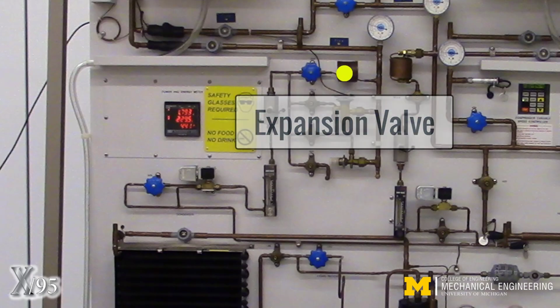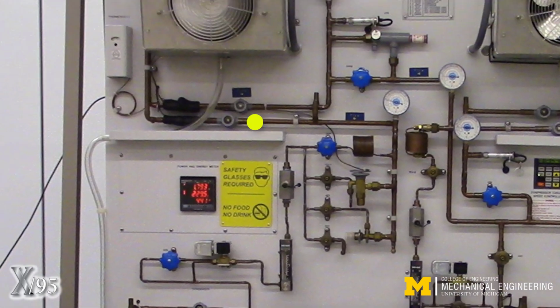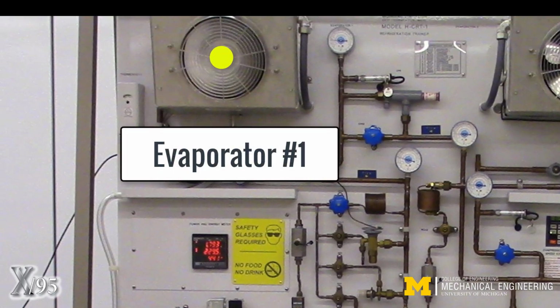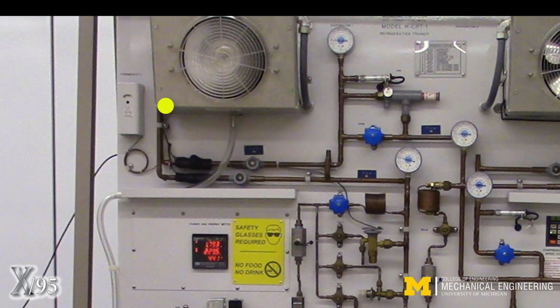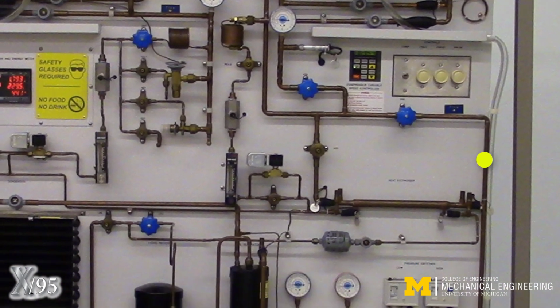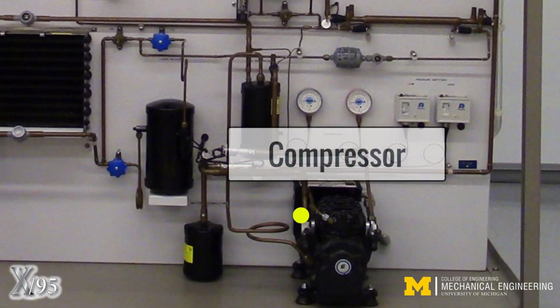Then the freon flows onward to the evaporator. Use the sight glasses to inspect the freon state, i.e. liquid or vapor, entering and exiting the evaporator. From the evaporator, the freon returns back to the compressor to complete the circuit.